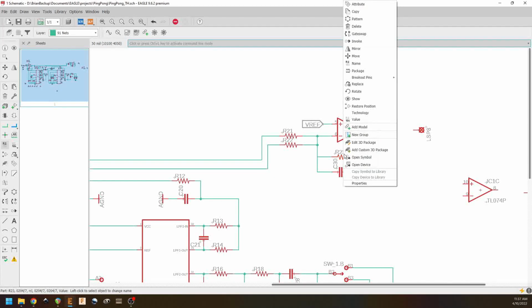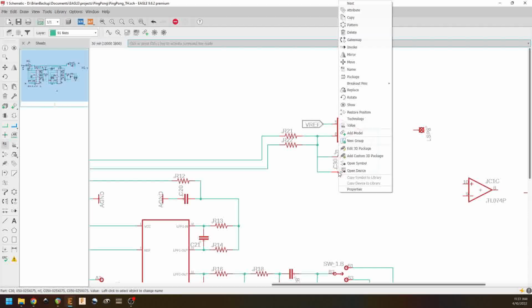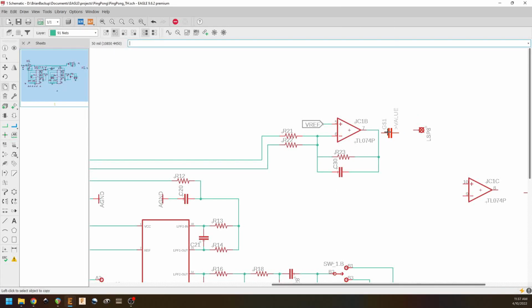And then we're going to add ourselves a DC blocking capacitor here. Make just a little more space. And then we're going to put in a very small voltage divider here. This isn't going to do very much to the actual signal level.